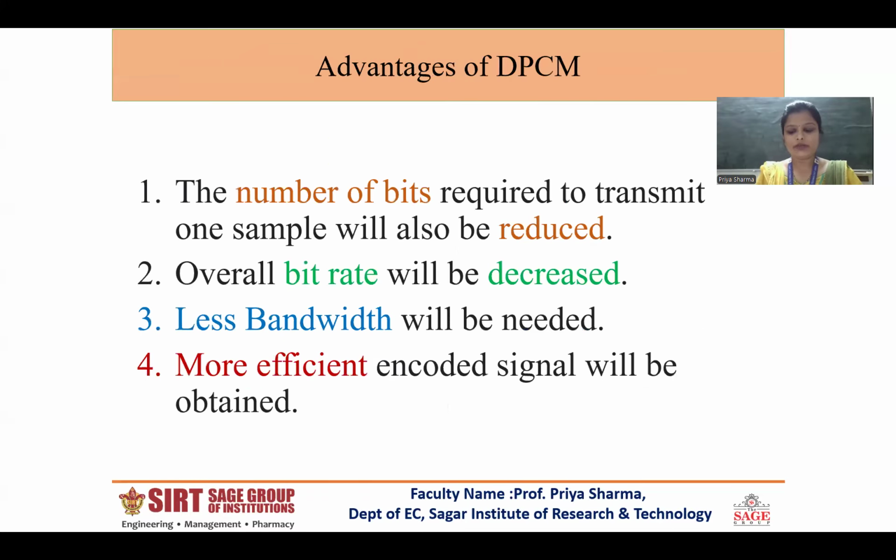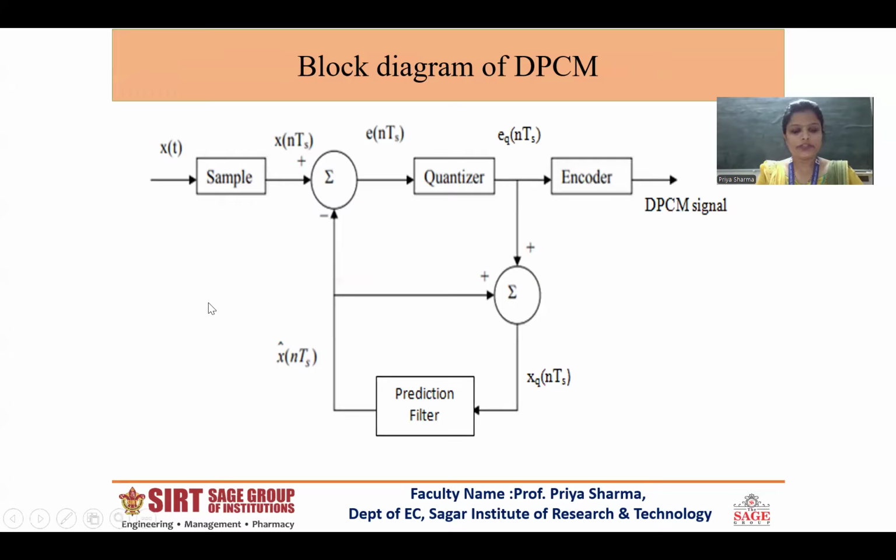Now coming to the encoding and decoding part of differential pulse code modulation. Basically, the analog input signal is band limited to half of the sample rate. So sampling takes place here. It is then compared with the preceding accumulated signal level in the differentiator. Here it is compared. The feedback loop, or the accumulator, comprises a binary adder, digital to analog converter, and integrator.